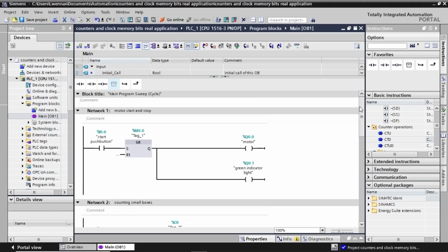It remains to put them in the right place. To stop the motor for a period of time, we use a closed contact before the motor and assign it with the timer's address. We stop the motor until another start, either by a press on the stop push button or the counter down output. Thus, we drag 2 contacts to the reset and assign them with the stop push button and the third memory address, which retrieves the counter down output.